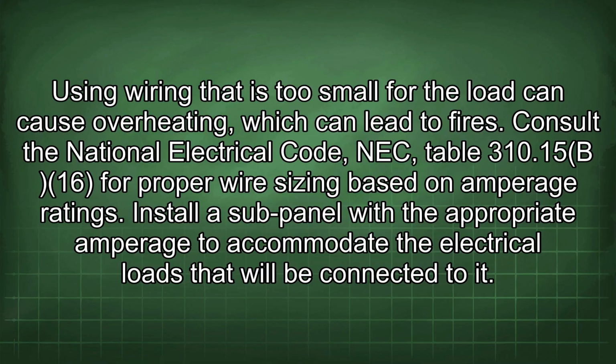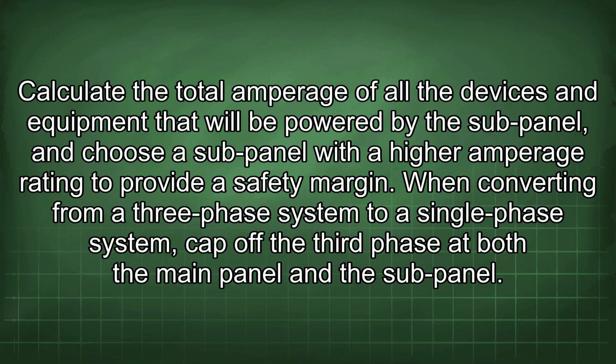Install a sub-panel with the appropriate amperage to accommodate the electrical loads that will be connected to it. Calculate the total amperage of all the devices and equipment that will be powered by the sub-panel, and choose a sub-panel with a higher amperage rating to provide a safety margin.